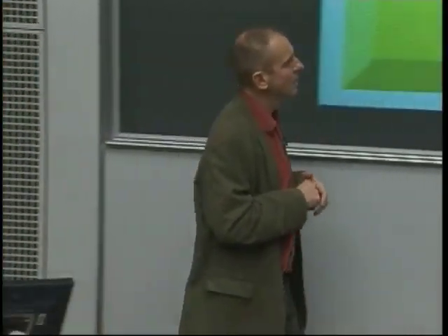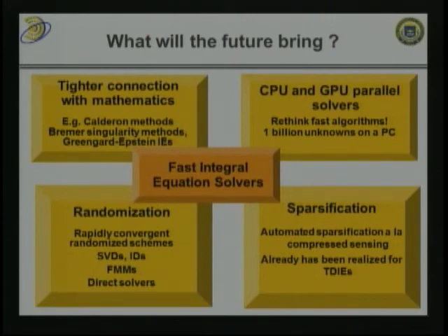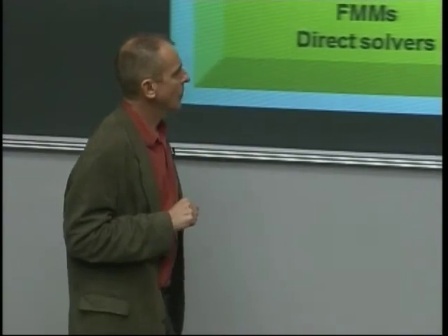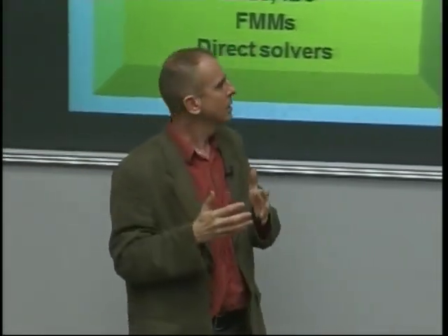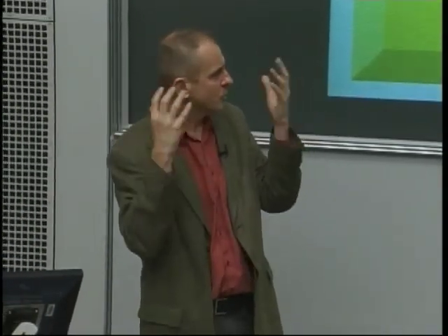And then last but not least, sparsification. Everybody here, of course, has heard about all the L1 buzz and compressed sensing and things like that. There is no doubt in my mind that not too long from now, many of these ideas will make it into computational EM tools. We have recently demonstrated, I think, the first rigorous high-frequency time domain integral equation solver, a solver that seamlessly transitions from low frequencies, where you describe the fields mostly in terms of currents on objects, to high frequencies where you describe fields in terms of rays.